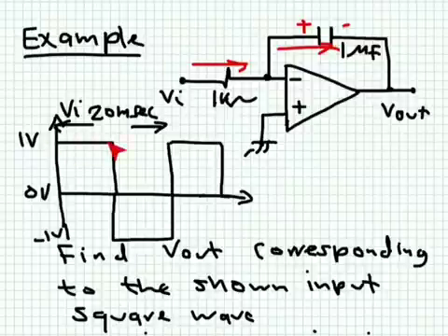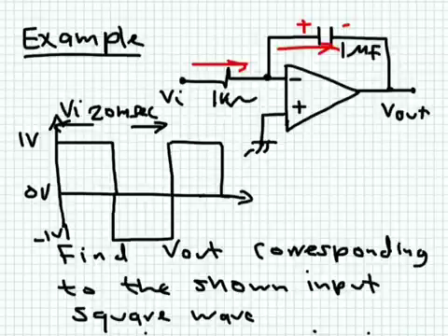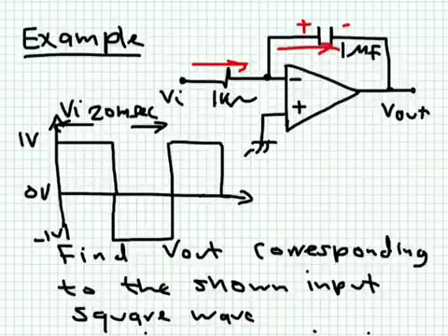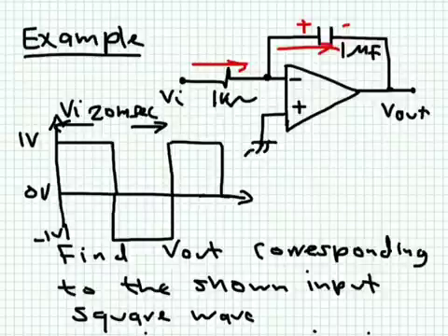When you have this 1 volt in this part, it's a constant current. And when a capacitor is charged under a constant current, I will show you in a second that the voltage increases linearly with time. We have seen before that if it's charging through a battery, a voltage source, it charges exponentially. Here, when it's charging through a current source or a constant current, it charges linearly.